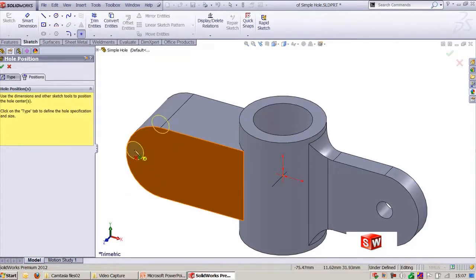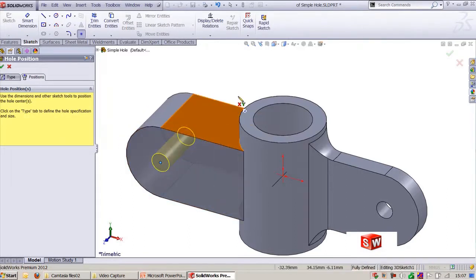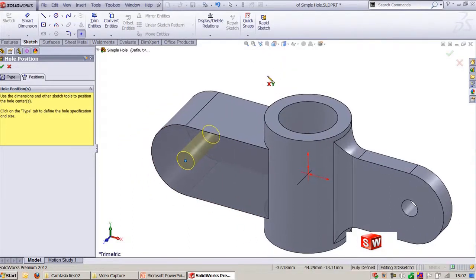position this. When you are positioning this, you can see here you will be able to get exactly center point of the existing edge. And you need to locate one more circle, that is one more hole. Yeah, you can locate this. How many holes are required, you can locate randomly. And once you finish this, you can right click and you can get dimension.